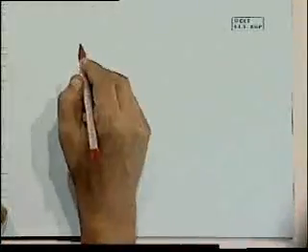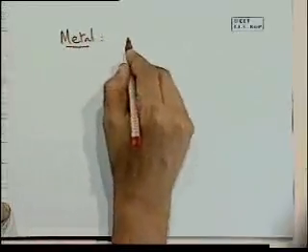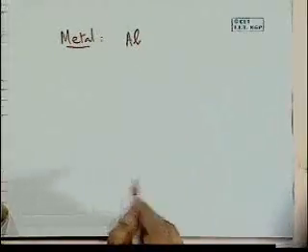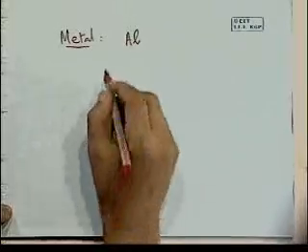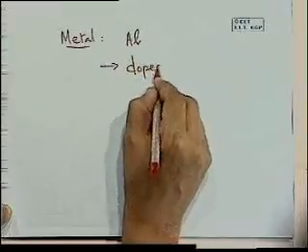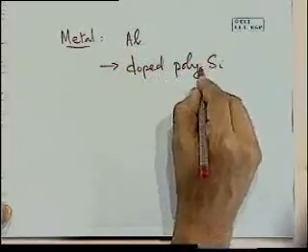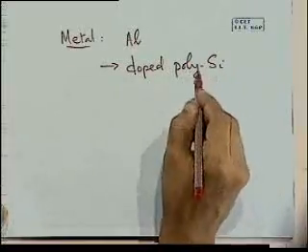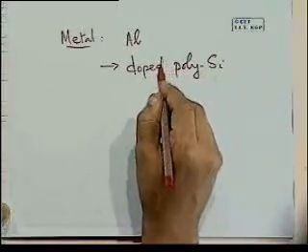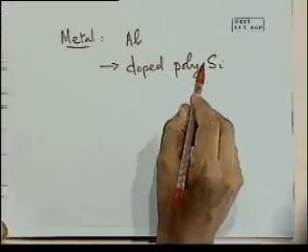P substrate doping is low. The typical metals that are used as the contacts, aluminum is the most common one. You can also use doped, highly doped polysilicon. You'll find this term polysilicon. I don't know if I used it before. Basically, polysilicon refers to polycrystalline silicon.